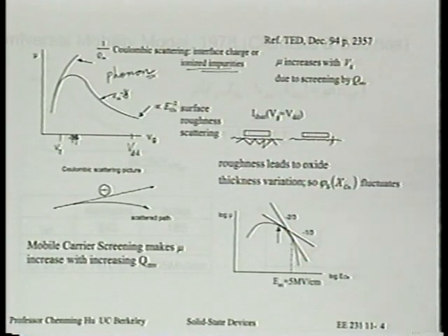At most by a factor of 2, right? It's proportional to VG minus VT. So you lose your mobility by more than a factor of 2, even though you increase the charge by a factor of 2. What can you expect for your ID set? You're supposed to see less current with increasing VG, right? So when you really look at this curve, all kinds of questions come up.